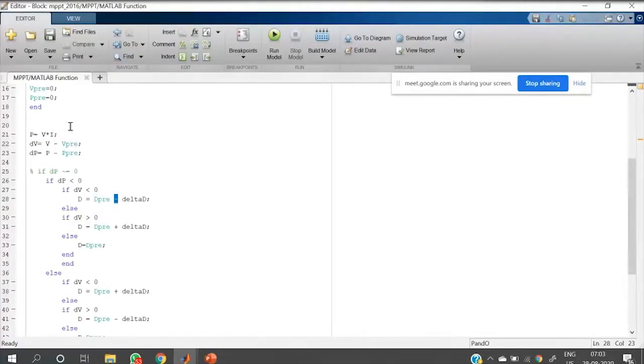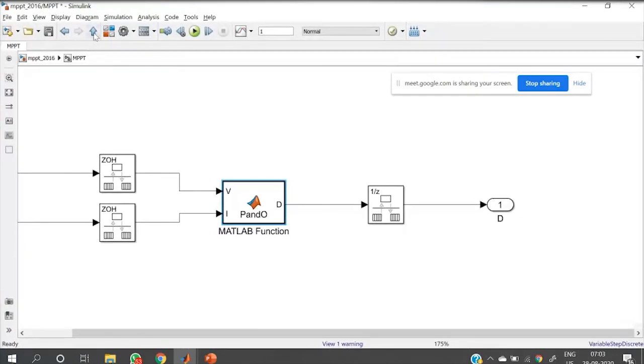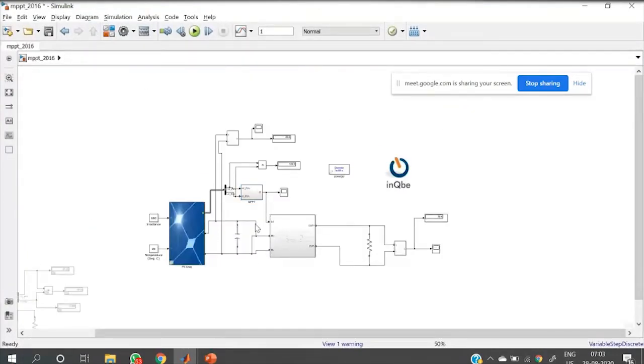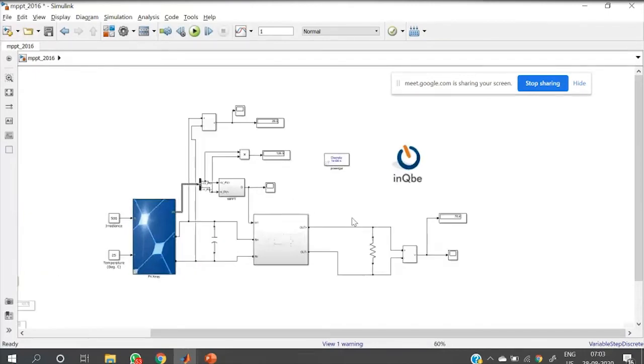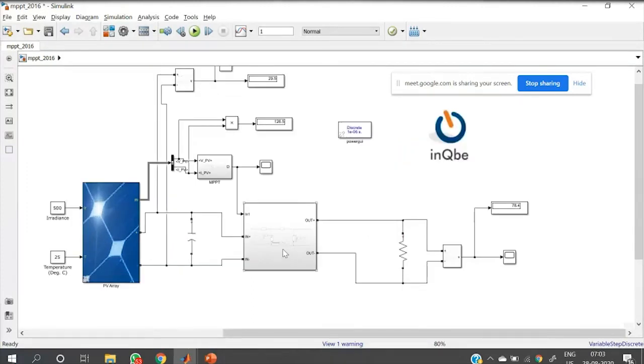Duty cycle has a range of 0 to 1, but in the case of voltage, we have to identify the range of voltage in the PV. Then we can apply upper and lower limits, convert that into the corresponding PWM voltage, and that voltage will be applied as the command for the control loop.